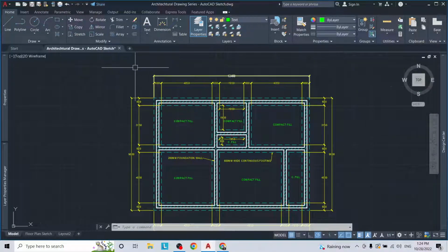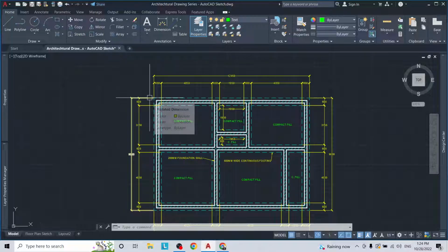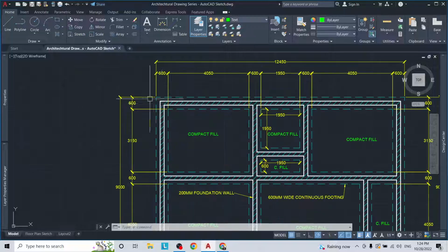Just one thing real quickly, usually for these drawings, when you want to show some details, when you're doing your detailed drawings, you'll have to show what portion of the drawing that we're getting our details from. So for example, if I'm going to show a cross section of this strip foundation, I can draw a circle around it like so.